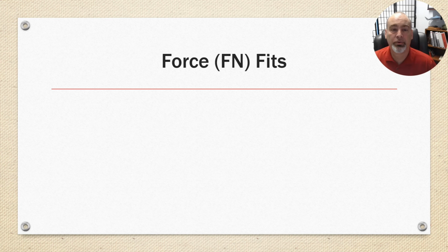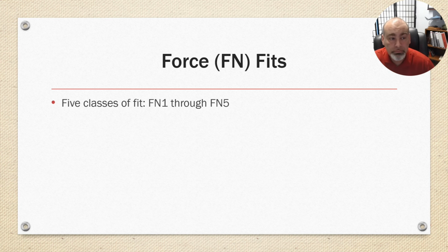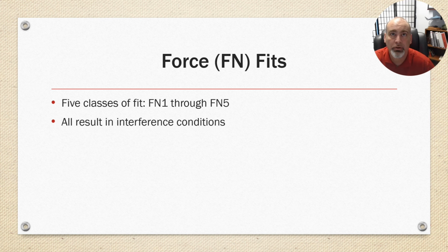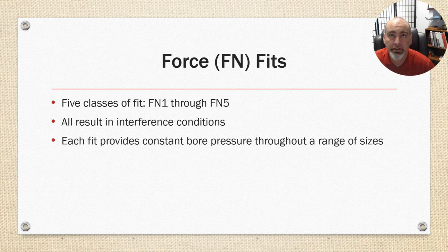Now we have the force fits. These would be for rotating parts, transmitting power. There are 5 classes of fit. FN1 through 5 all result in an interference condition. Each fit provides a consistent bore pressure throughout a range of sizes.